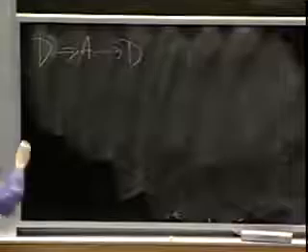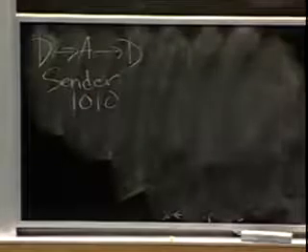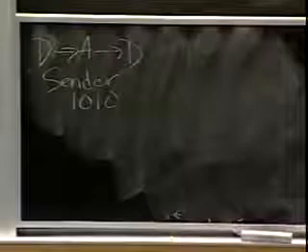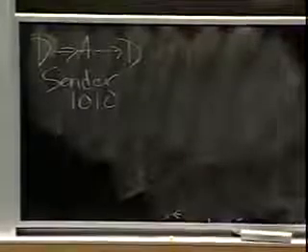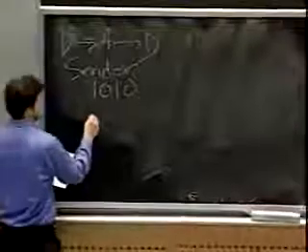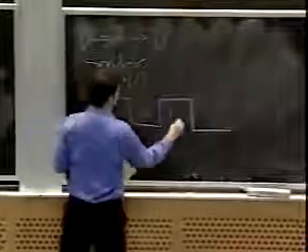The first issue is how the conversion from digital to analog works. Suppose that we have some sender which has some sequence of bits, say 1010, that they want to send out over the radio channel. There are many different ways you could represent this as an analog signal, but a simple way might be to transmit it on a digital line, making the line high when we're transmitting a 1, and low when we're transmitting a 0. So we would send this message out as high, followed by low, followed by high, followed by low. So this would be 1 0 1 0.